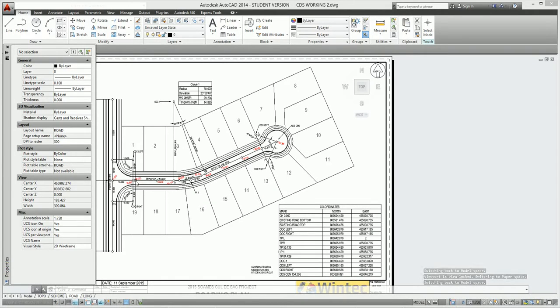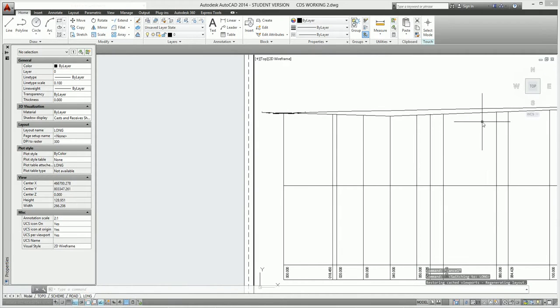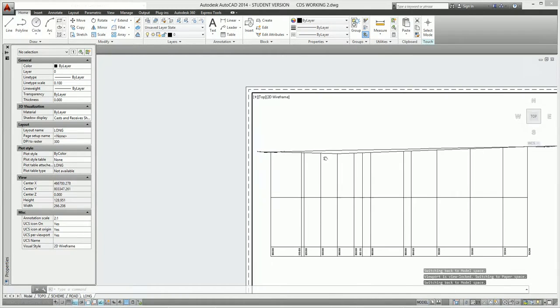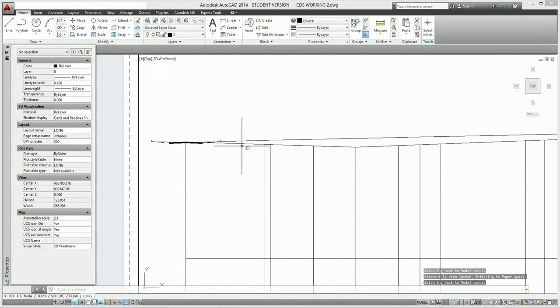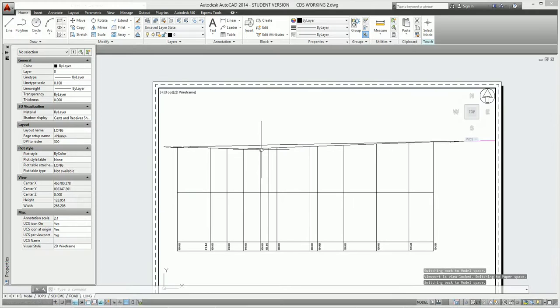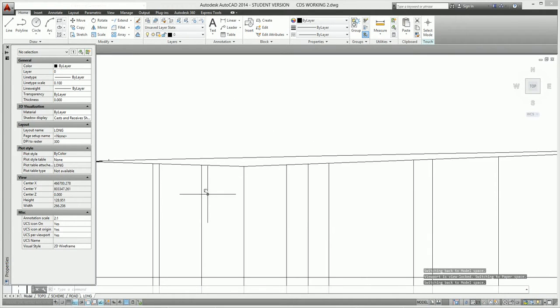So we've got to put some sort of vertical curve in at this point, because we're going to come down at that, and then we're going to put in another grade going up the way to the cul-de-sac head. And then we've got to gently come through there.